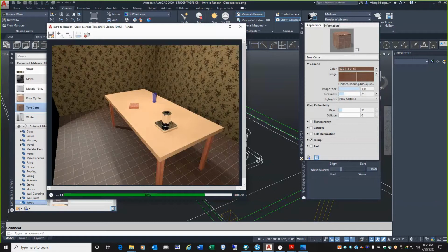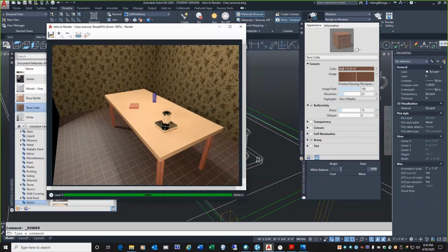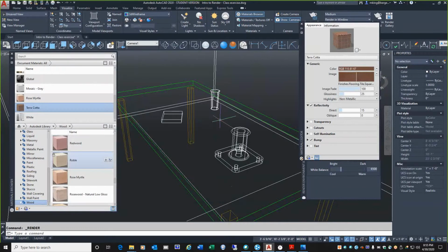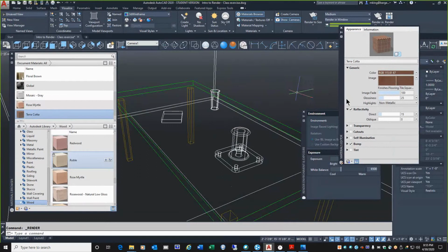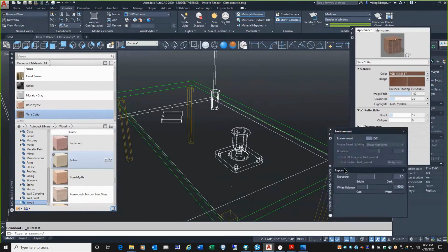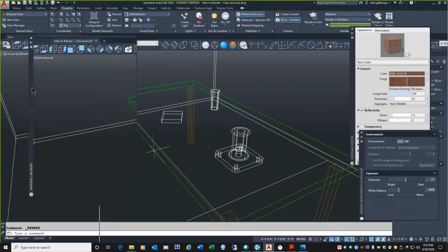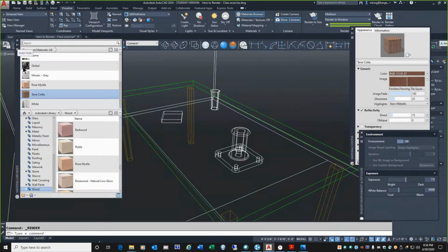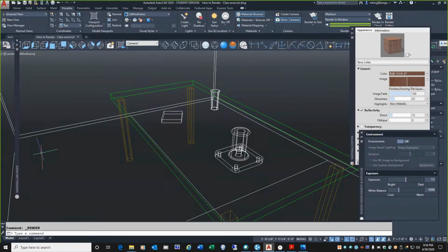Okay, before we go to the last topic, I want to show you how to change the grain direction of the tabletop so that the grain pattern is in the long direction of the table. Okay, and this is a little tricky, but this isn't even actually in the topics list, but I want you to see this because there's a lot more, and if we have a couple more classes to go, I would do that. But this is formally called mapping.